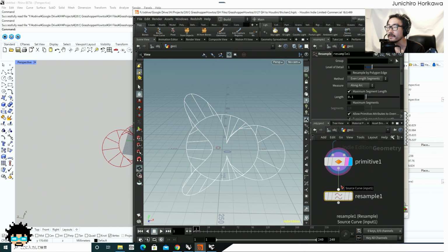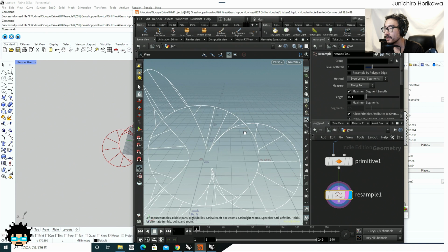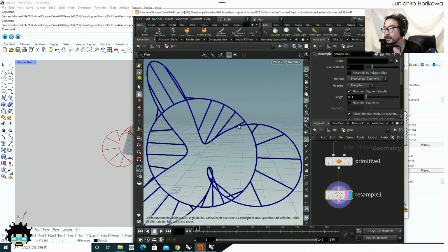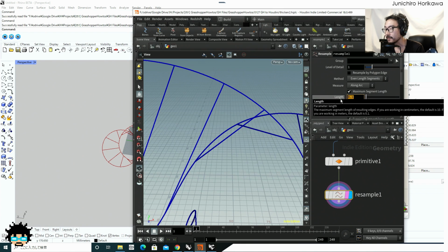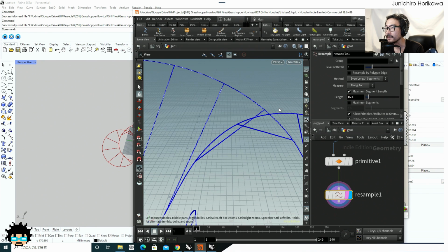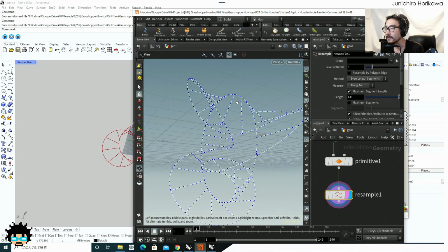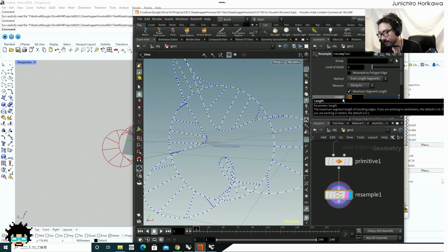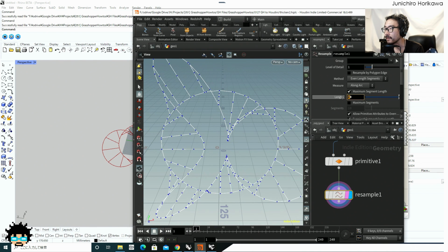It's similar to a rebuild component inside Grasshopper. Now you need to choose the length of the step for the conversion, and you can check the resolution by turning on this point toggle. I'm gonna set 0.5, maybe that's too big. Maybe 10, maybe that's too dense. 20 might be good. 30.